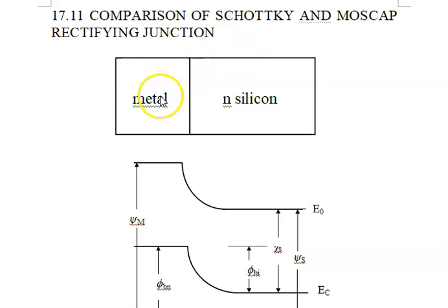This Schottky barrier, metal, silicon, in this case, N silicon. I know it's N silicon because the bands bend up in the depletion region. Here it's heavily N-type in the bulk, and here in the depletion region it is less N-type, and it can go, in fact, to intrinsic. Notice, and this is very characteristic, whenever we have a metal, we're probably going to have sharp corners.